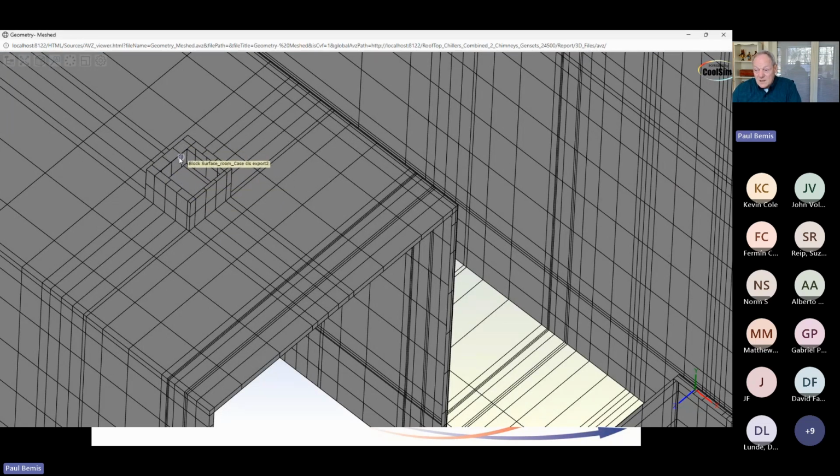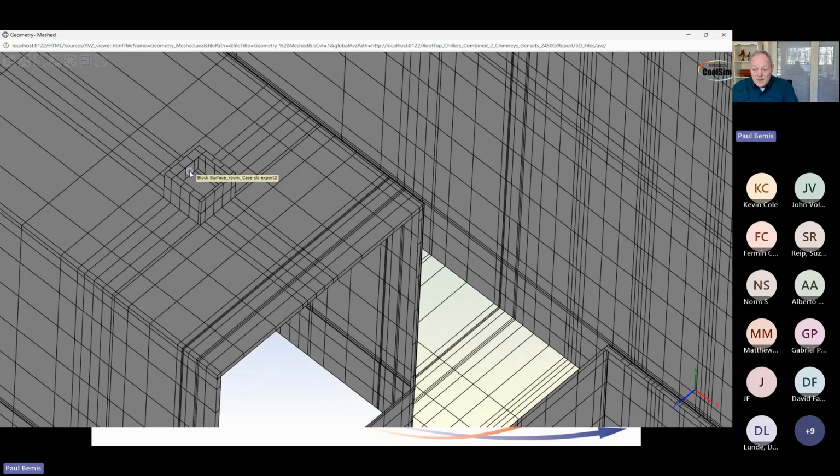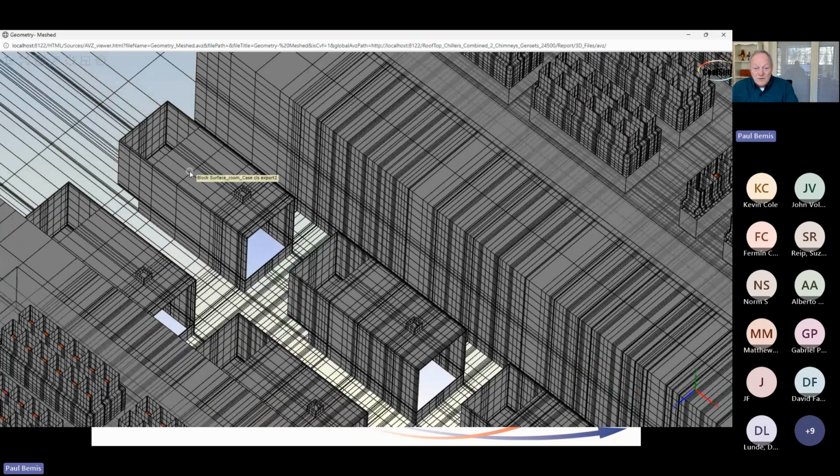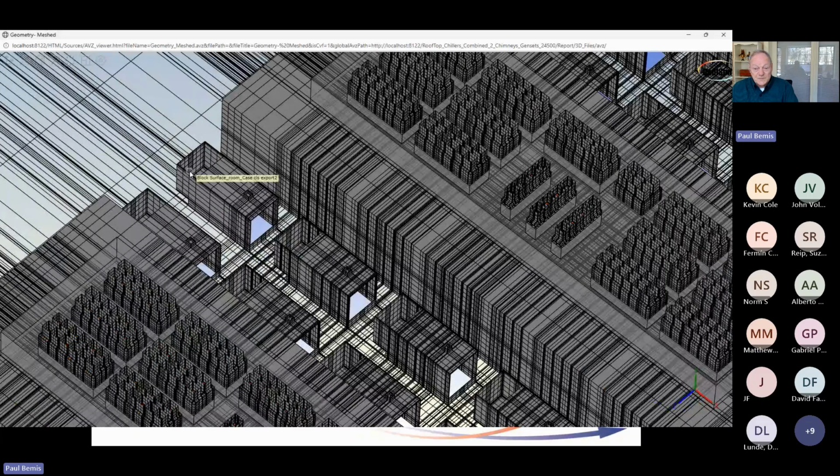I have 9 cells in there, so that would be 9 different points of integration, summarized and integrated over a surface. When you try to measure the exhaust temperature of a diesel gas engine, if you're lucky, you're using a probe and you're getting 1 point. So you have to be reasonable with your measurements in order to understand. But to answer the general question, yes, this technology maps very well to measured data, as long as the mesh is sufficiently dense, it will match quite well.